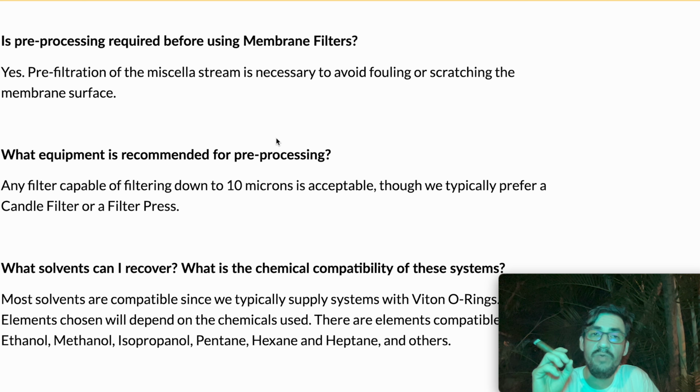Is pre-processing required before using membrane filters? Yes, you've got to pre-filter. You've got to filter the stuff and get all those big bits down, 10 microns or whatever. You can use a filter press, which is what we recommend. You can use a candle filter, which we also recommend. You can even use a bag filter, which I don't particularly like.